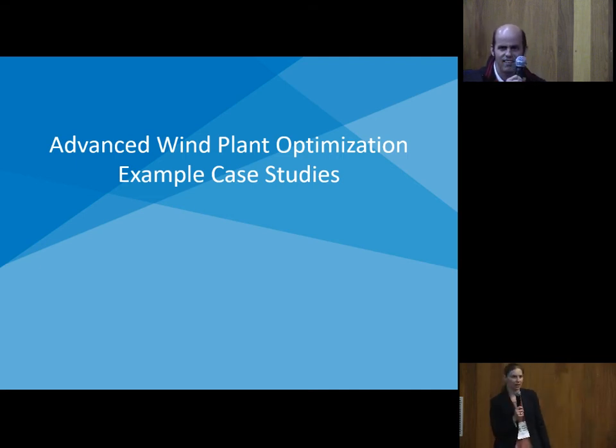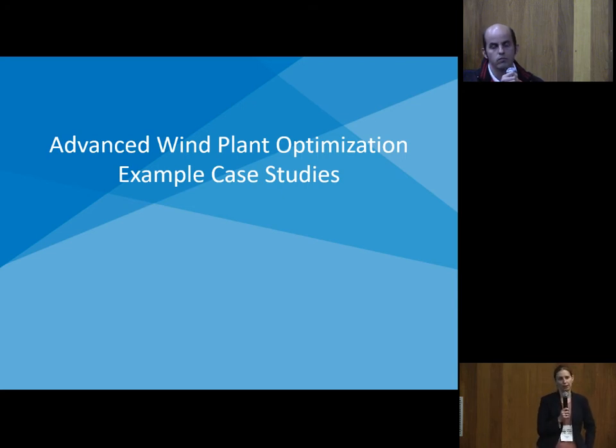So the short answer is yes. Some that I can speak publicly to and others that I can't. So we're working with both OEMs and owner-operators on wind plant controls generally and the wake steering with yaw controls specifically. Right now we've been doing a demonstration in a plant in Colorado with GE turbines at NextEra, which is the biggest owner-operator of wind in the US, basically demonstrating the wake steering on a subset of their turbines. We've done that with other manufacturers as well. Some of those we can't disclose.